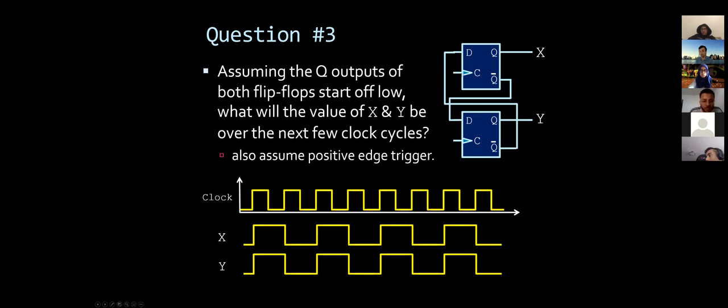And then you use the clock edge. It's activated when the clock goes from low to high, and that's what happens here. It goes up, so that triggers the output here to go up. And it's going to stay like that because the second part here serves as a proper secondary flip-flop for it. So I built something tricky here where each part serves as a first blocking part for the other in terms of flipping the value. If you start with two zeros, then they both are going to flip here at the positive edge. Then they're going to stay like that until the next cycle, and then they're going to go down.